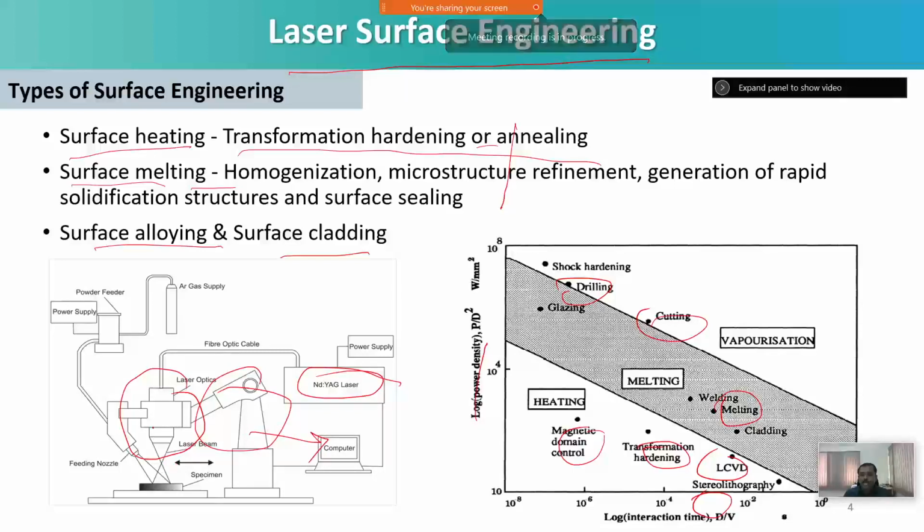So when you want to cut any material, normally you can place the workpiece in the focal point, and when you keep the workpiece at the focal point, you can get the maximum energy available from the laser.